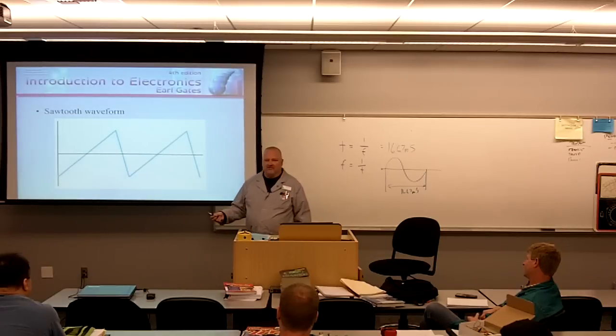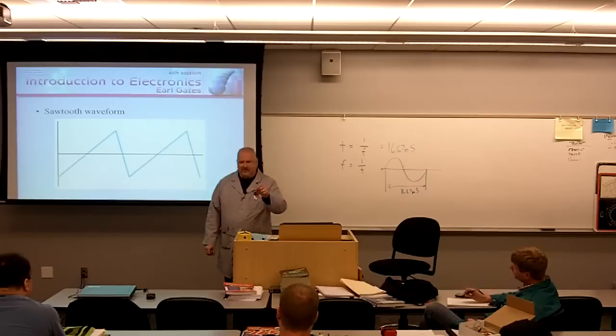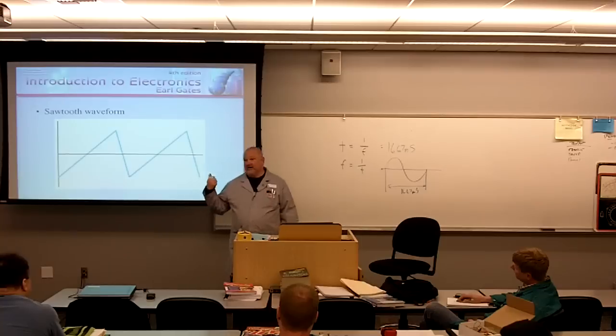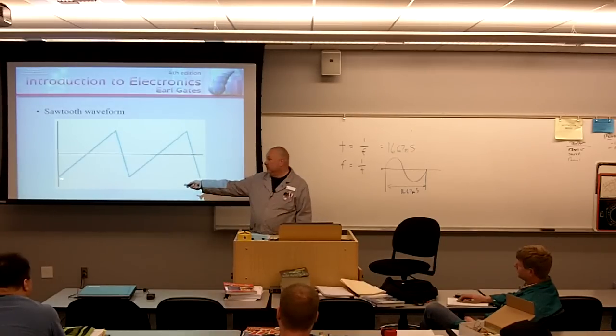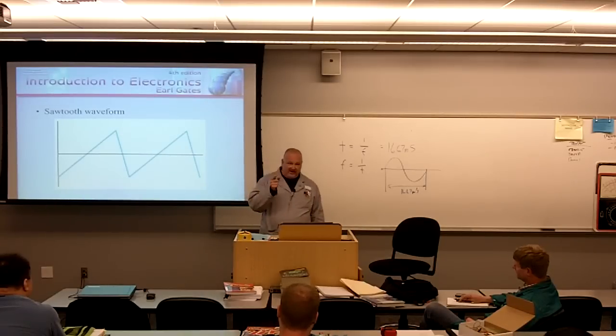When a sawtooth generator fails, you get a dot in the middle of your screen. You turn your TV on, you got a dot in the screen. That sawtooth generator probably has failed. Same thing with your oscilloscope. That's how an oscilloscope works. When you get a display up, basically what that display is that beam getting pulled left to right across the face of the oscilloscope. It's a sawtooth generator that's creating that. Low voltage to a high voltage, and then rapidly resetting it faster than the naked eye could perceive it.